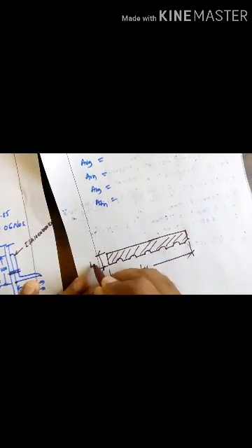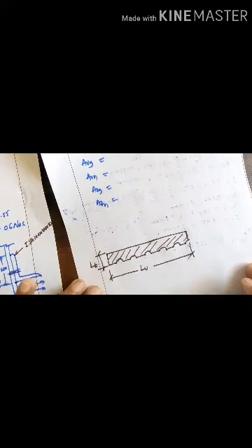The plate may come out like this. So shear area means from here to here, the last center. Then the tension area, this is the tension area, that is LT. I hope you understood this one. This I explained in previous problems. This is the shear area along the load. This is the load direction.